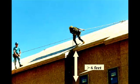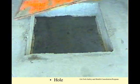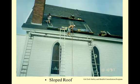they are working at 6 feet or more above a lower level. Additionally, fall protection must be provided any time an employee is working over dangerous machinery or equipment, regardless of the fall distance. Fall protection is required when working on open sides and edges, when performing leading edge work, on sloping roofs as seen here, during residential construction work, around holes like the one pictured here, including skylights, as well as excavations and wells. Fall protection is also required during overhand bricklaying, work on steep slope and low steep roofs, during precast concrete erection, and formwork.